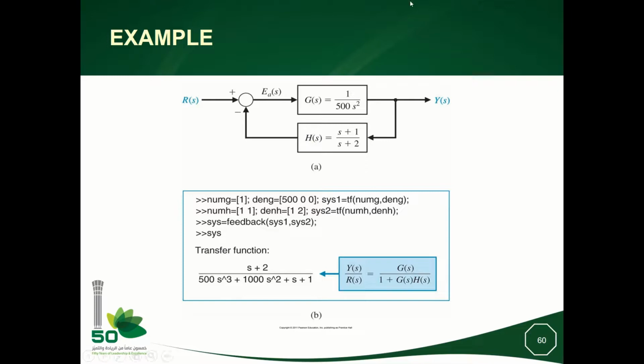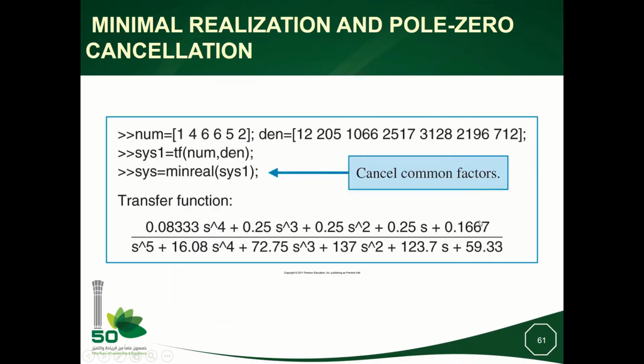So this is just a direct application of the feedback command of MATLAB. In the first line here, we are defining this G(s), and here we are defining the transfer function H(s). And at the third step, we are composing the transfer function Y(s) divided by R(s), which is given by the instruction feedback. So this gives the results which are shown here.